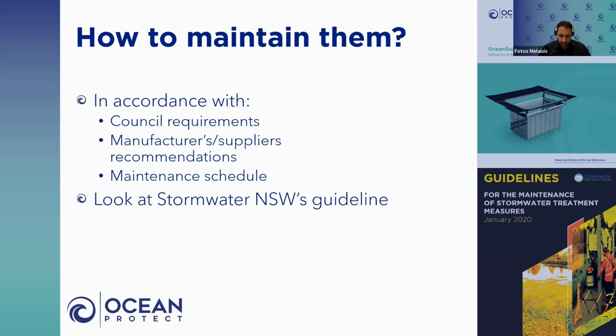Biofiltration is another one. You might be looking at simple processes such as landscaping contractors adopting the removal of invasive weeds or the replanting of native species. Another monitoring tactic that could be implemented would be to monitor the system for 48 hours after a major rainfall event to see whether it's draining through the filter bed media. And these type of things can determine what level of maintenance needs to be accounted for in the future.